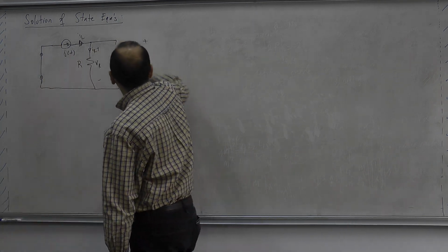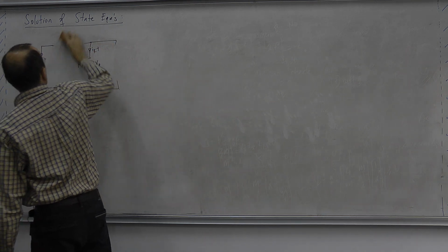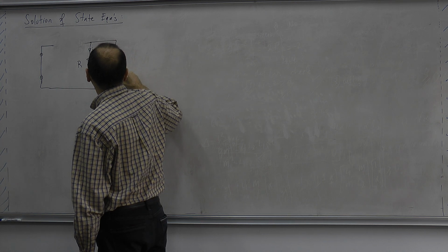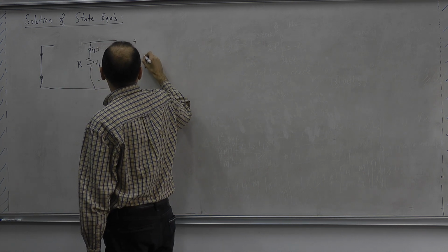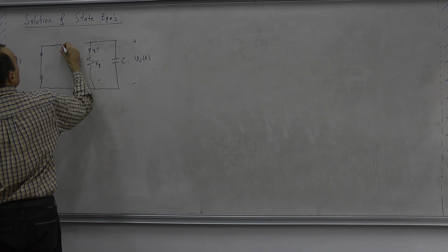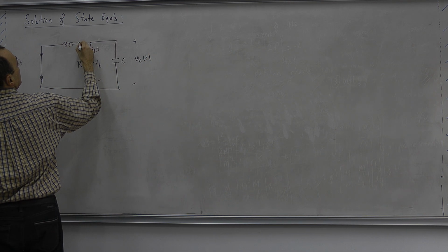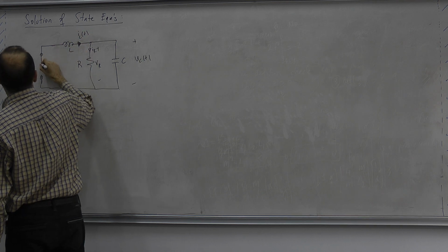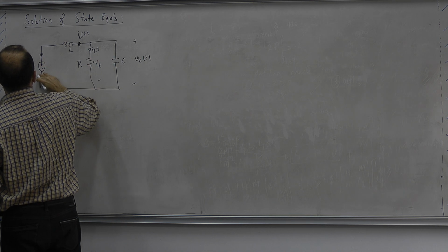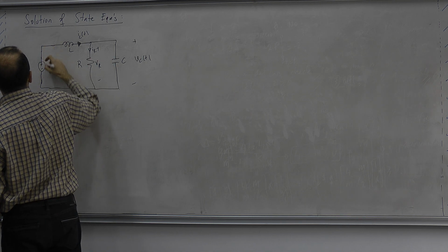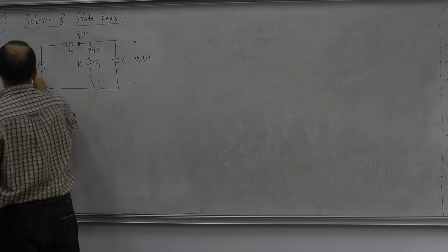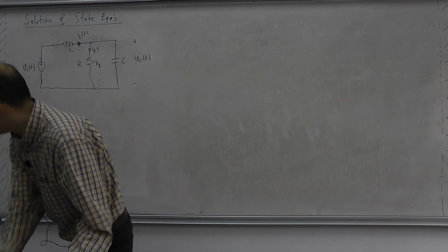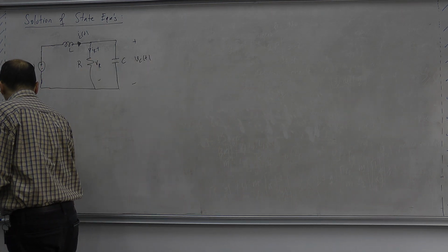Okay, so what did we achieve? We have achieved the following. After this visual inspection essentially, because you don't need to erase and draw one more time every time, we have set the order of the circuit. We have determined the order of the circuit as 2. Okay, so this is indeed a second order circuit. So this second order circuit, we have seen how to represent this circuit in the state formalism.